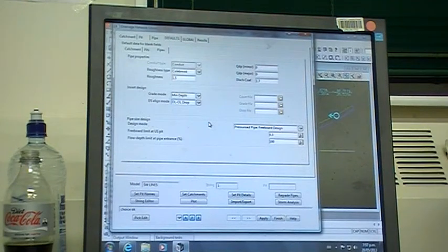If I have a 450 here, and this is a 375 coming in, the council standards require that the obvert, or the top, of that pipe has got to line up. So the drop then is going to be, you know, 450 minus 375. Standard pipe, okay, but most of the standard pipe sizes tend to go up in 75 mil steps.